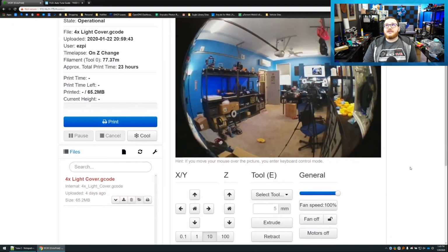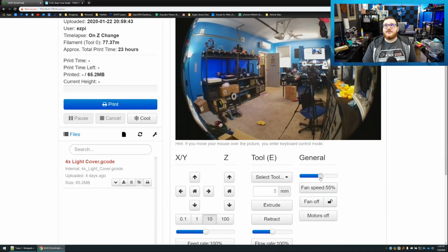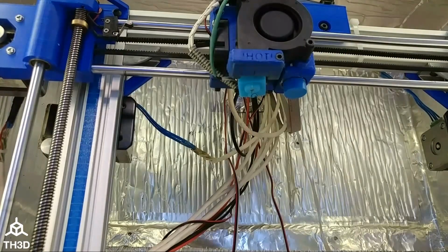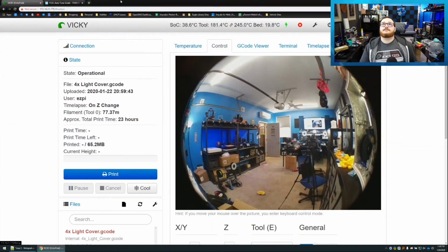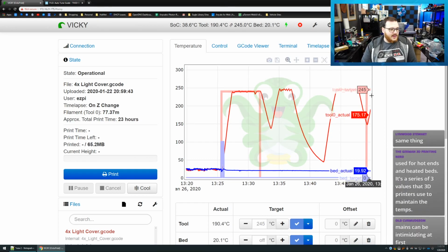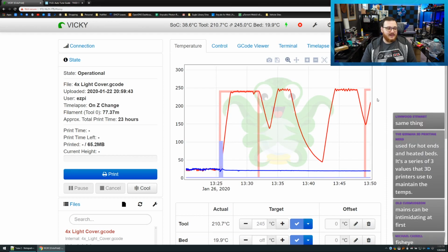My hotend fan should still be at 100%. It is. I'm going to drop this down to 40 because that's what I run on this machine for ABS. If I switch over to the V20 here, you see we're still spinning, it's just slower. And what I want to see here is what it looks like once it levels out. I think the PC power supply is a little safer, I guess. I mean, it's only dangerous if it's plugged in.